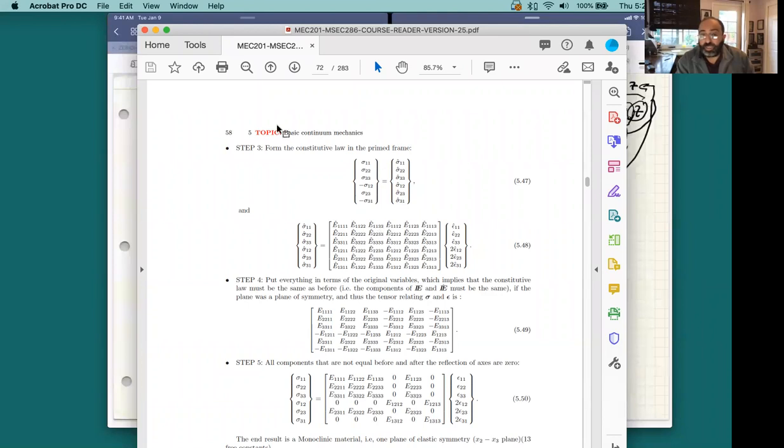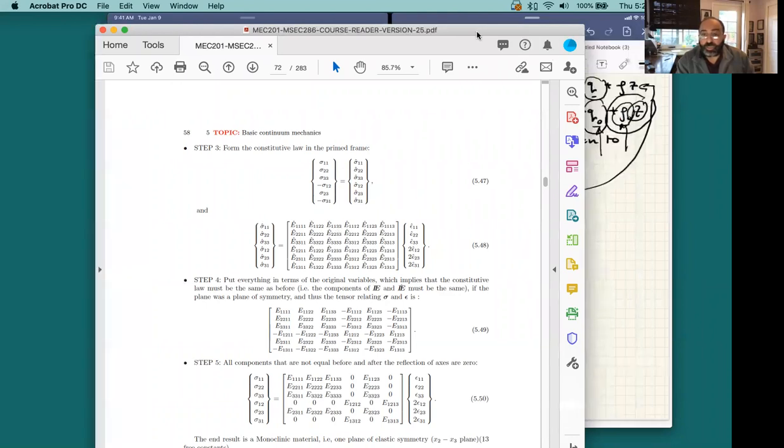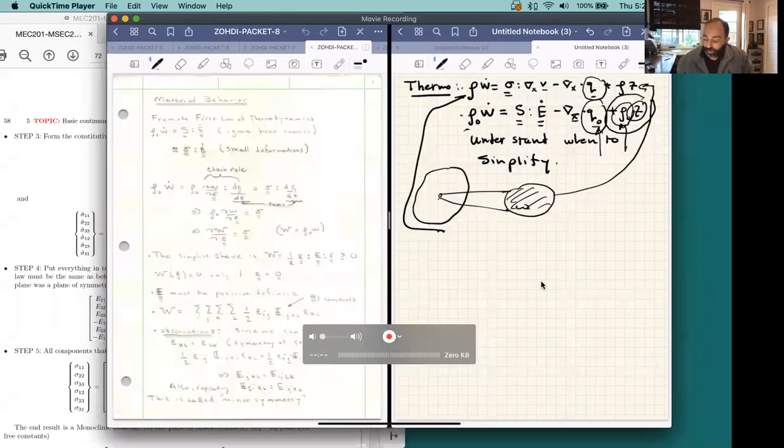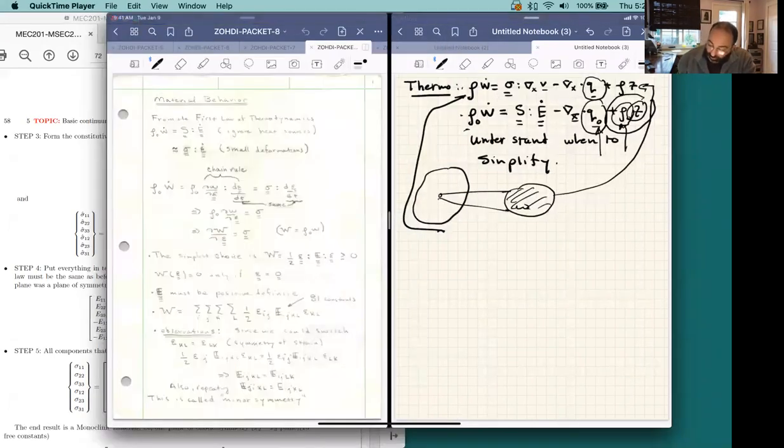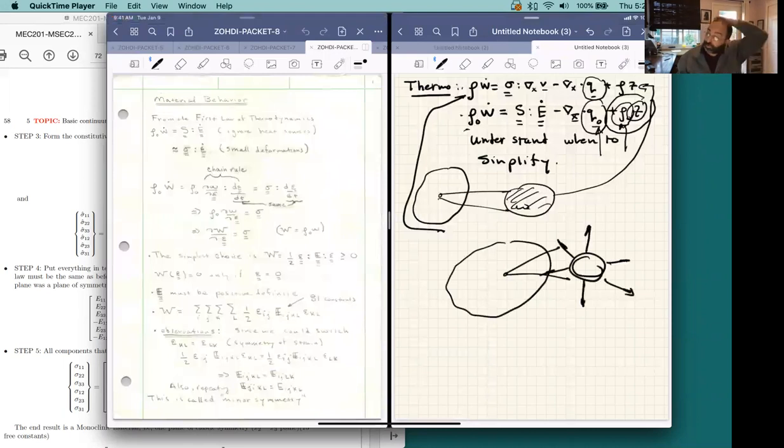material. So basically, anisotropy is a concept that basically, let me write as we're talking, basically states the following. If I have a piece of material and I come along and I isolate a little section of it, if I were to pull on the piece of material in different directions, depending upon the directions I pull into, the responses will be different. However, in the unique case, which is very prevalent in many branches of mechanics and so forth, the material roughly behaves the same when pulled in all of the different directions.